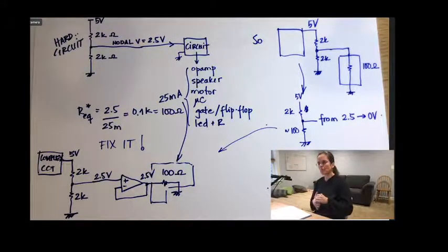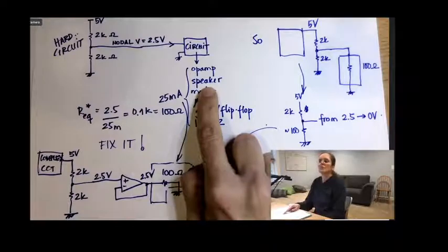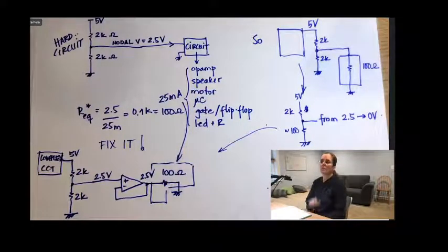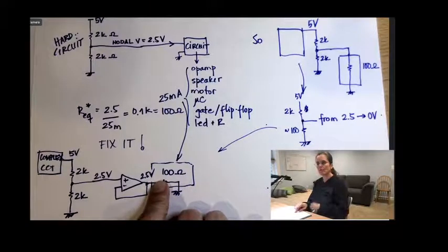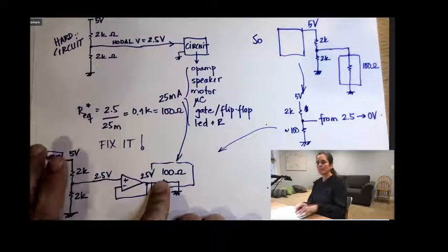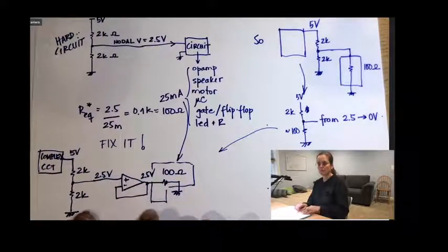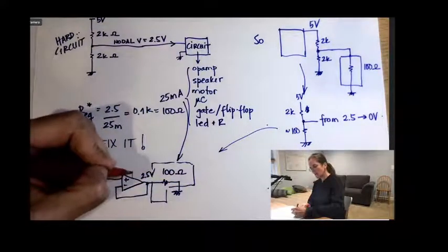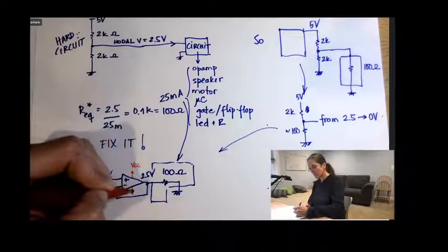Usually op amps will go to 50, but you can design the op amp so that you have enough current on the output that can deal with the load. If it's a speaker for your car, you want to use an audio amplifier that will put out at least 1 amp. If it's a small motor, you look at how much current it needs, which voltage, and then you can even change this voltage and it will change it here. It will not be using any current from your original circuit and will provide its own current that really comes from you giving power to the op amp.